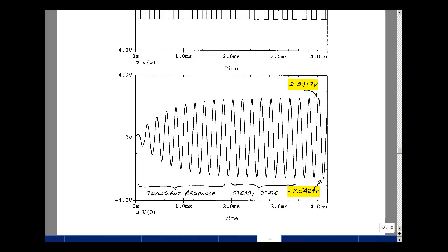But this is what it means to be a filter. You pull a signal out of a bunch of signals. In this case, the square wave contains a fundamental frequency and odd harmonics, odd multiples of that fundamental frequency, which is 5.03 kilohertz in this example.